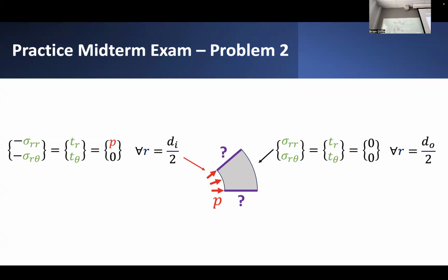So anytime we introduce a symmetry plane, we have to introduce this additional constraint on normal displacement across the plane being equal to 0. That's a good thing to commit to memory. You might want to remember that because you might need to apply it during the midterm exam.